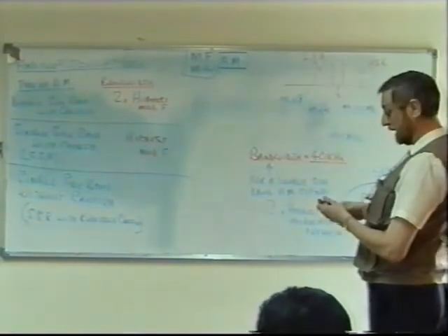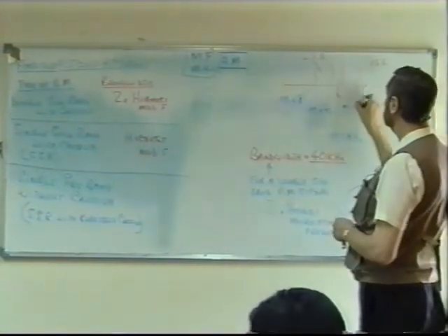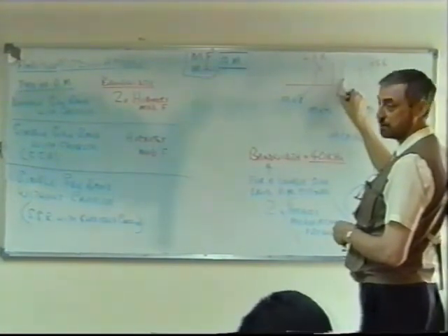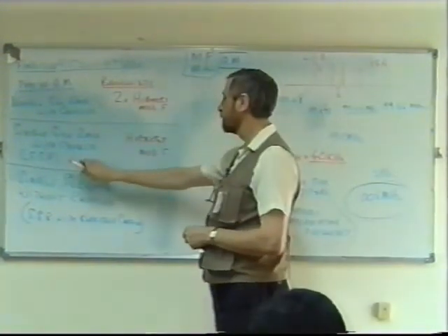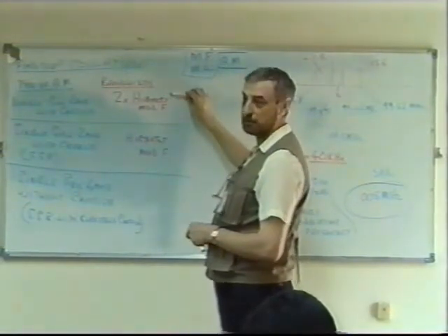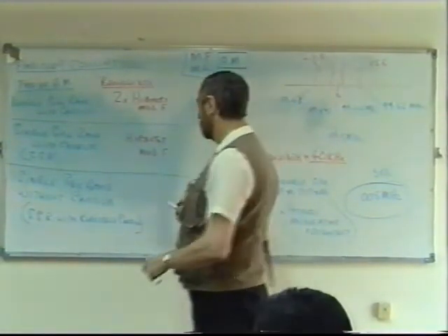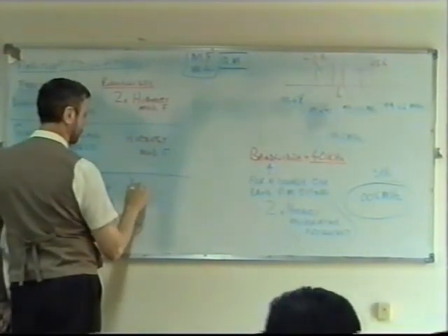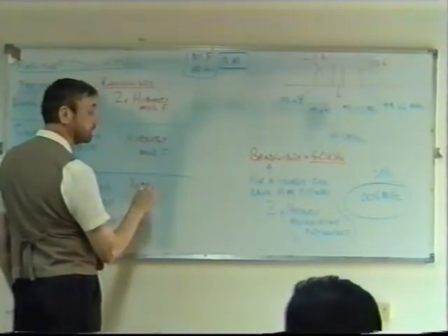Now the bandwidth is simply the difference between the highest modulating frequency and the lowest modulating frequency. Remember, the bandwidth here was simply the highest modulating frequency. Now the bandwidth here is slightly different. It's the difference, 15 in this case. Yes, that's right.